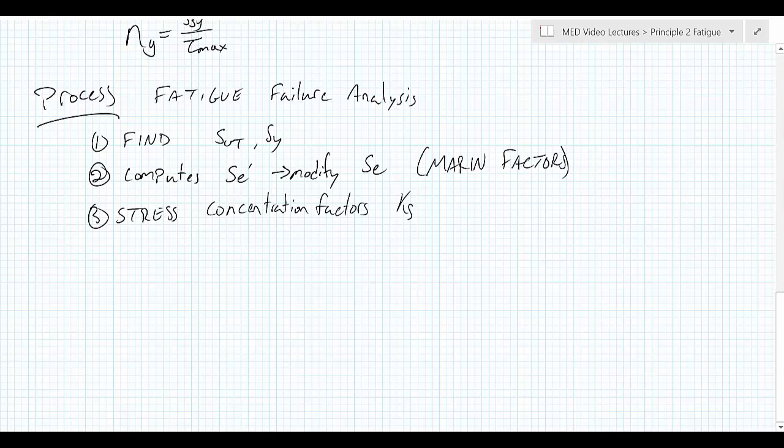Recall Kf is related to 1 plus q times Kt minus 1. And then we multiply our stresses by that factor.